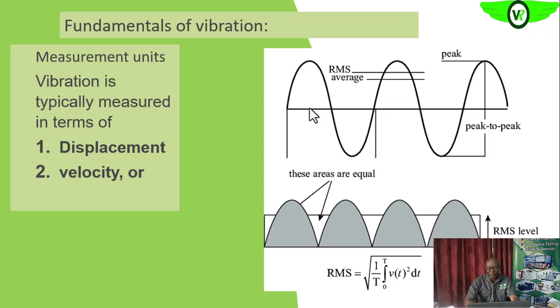Then we also have velocity, okay, which is the rate of change of this displacement per unit time. Okay, so the displacement, we can get like we said earlier, the vibration amplitude of the particle, while the velocity will give us more information about those low frequency events that, as we'll see later.